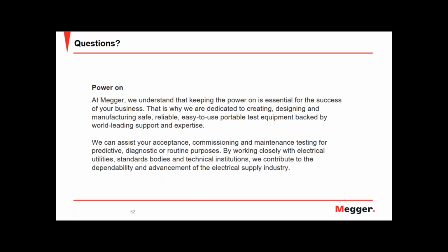The best option, of course, is to avoid the ingress of moisture. So if you're planning to have a prolonged shutdown, and you don't have these automated heaters, a common thing to do is to place a small traditional incandescent bulb inside of the casing where you have the equipment, and that keeps the moisture out, keeps things warm. And you can avoid that moisture with that method.